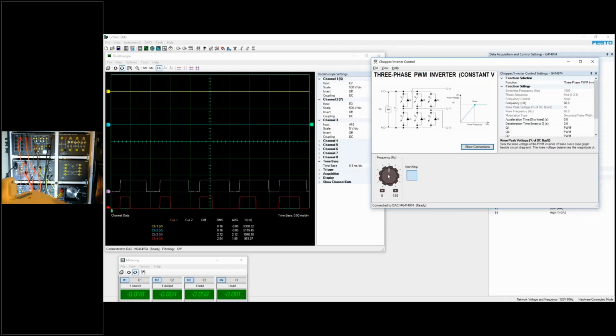But now I will decrease the frequency here, output of my motor, just like you would do with a variable frequency drive. As I decrease the frequency, the motor spins down. As you can see, it becomes slower and slower. And if I make it slow enough, you will see it spinning. You can see now that my output frequency is at 5 Hertz, and my motor is spinning really slowly. Basically, this shows to the students how to implement what happens inside a variable frequency drive. What is happening in there? Well, that's exactly what is happening.